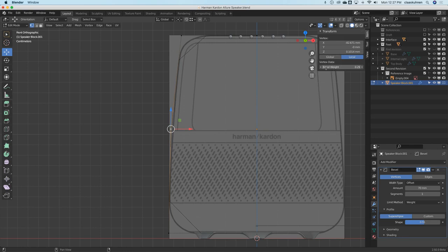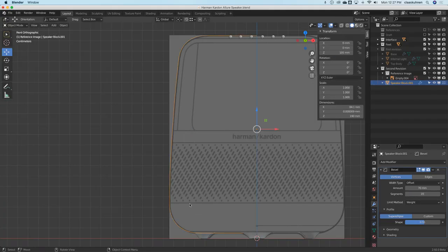And there, notice now, this is getting very close. You see how when I'm increasing the bevel weight for this midpoint, how the other fillet is being pushed up or down, because the fillets start to intersect with each other. This is not really that much of a problem.